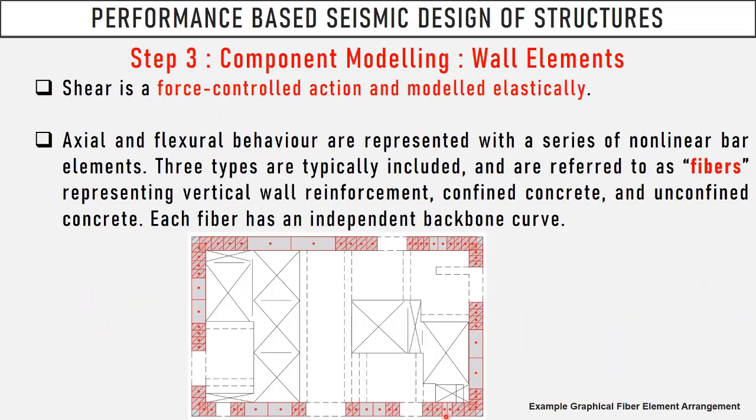For that, you need an approach for how to evaluate the nonlinear behavior of your members. As for these high-rise buildings, the core system is the major lateral load resisting system, and you need to refine your nonlinear behavior in your wall.